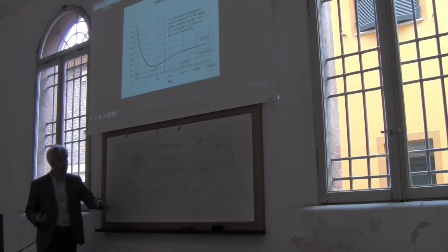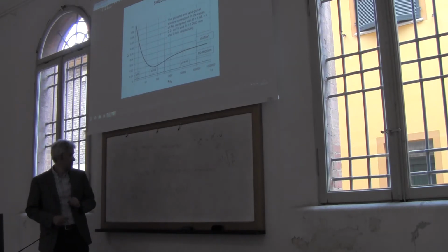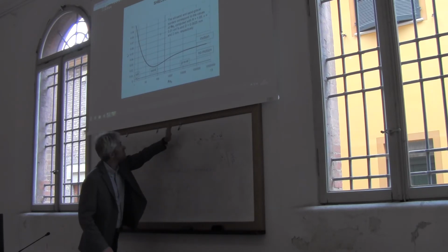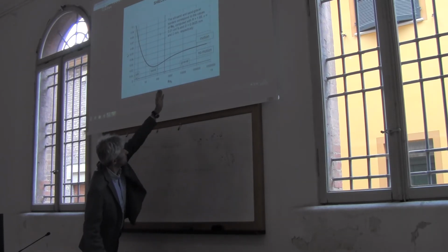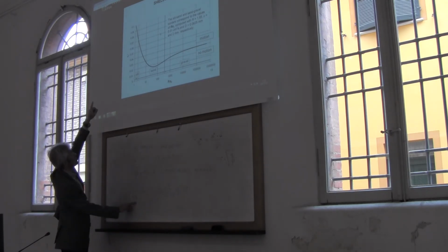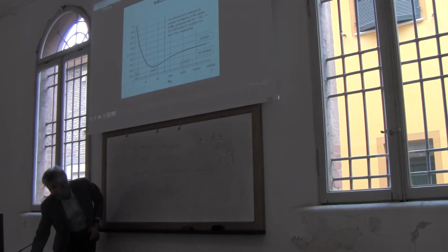If they are unstable, you increase the diameter. And then, if you increase the diameter, what happens? Okay, you have an increase of the Reynolds number, so you move in the right part of the diagram, but here you move in the lower part of the diagram, and then you get a stabilization. So if you were like here, for instance, in the first attempt, then you move to the right, and you move down, and you get to stability.